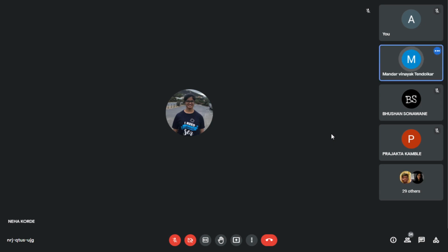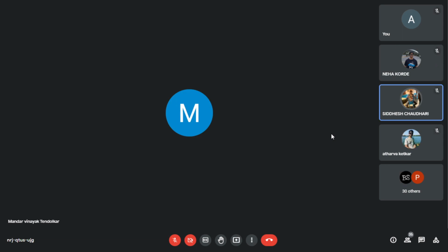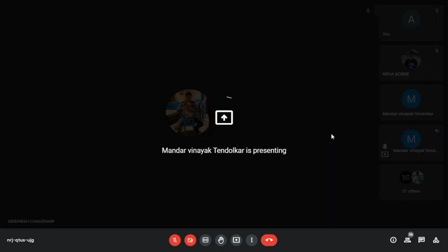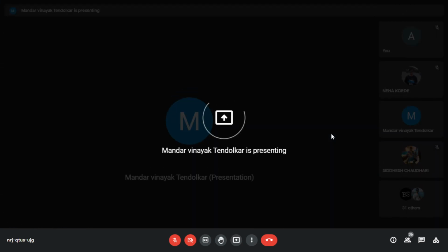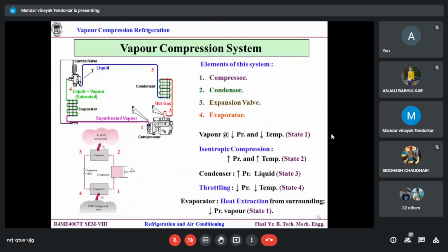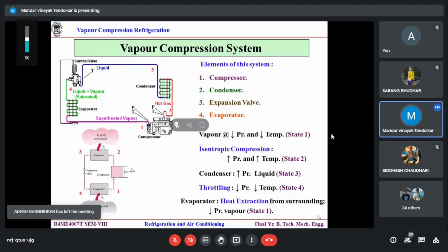In the last lecture, we had seen up to this part. Correct? I hope you recollect. So we discussed in the morning also in the lab session, our inlet condition to the compressor is low pressure and low temperature, basically atmospheric pressure and atmospheric temperature, let's say. Then after the compression, high pressure, high temperature. In the condenser, it is a high pressure, but not the vapor phase. It would naturally be a superheated part.